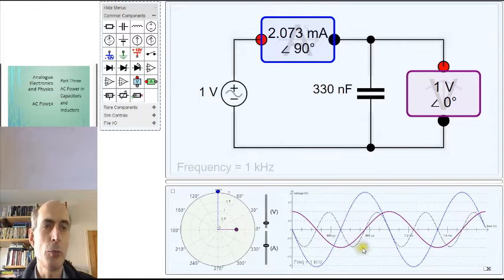It's an oscillating waveform. Again, it's oscillating at twice the frequency of our voltage source, but now it has an average value of 0. We have both positive powers and negative powers associated with this component. What about inductors?